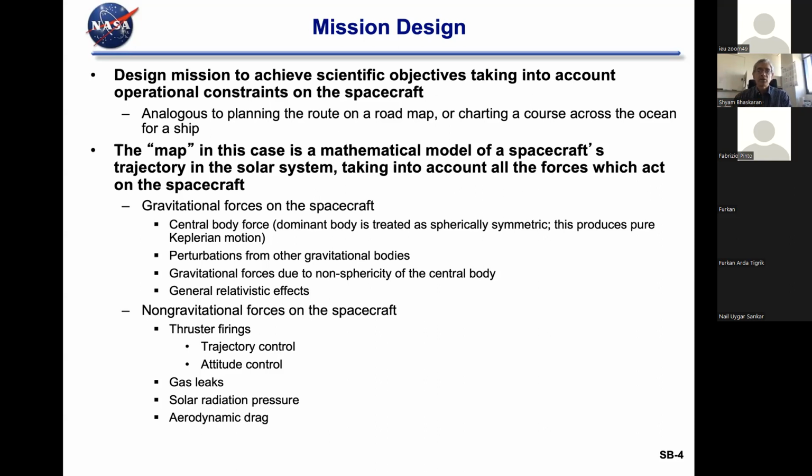There's solar radiation pressure. The Sun's photons out there actually have momentum, and that momentum pushes on the spacecraft. I think the previous lecture you heard was from Bruce Betts on the solar sail. That same force is used very nicely in solar sails to push the spacecraft. For us, it's actually a disturbance instead of something we use, so we have to take it into account. We don't have big solar sails that catch that much, but even our small spacecraft still feel some force from the solar pressure, and we have to take that into account.